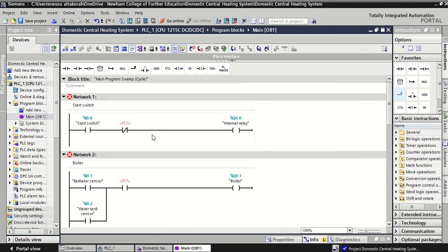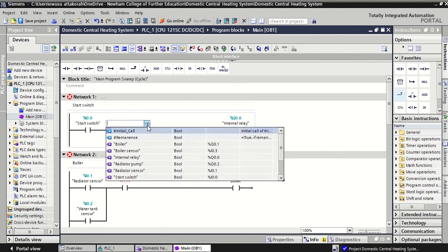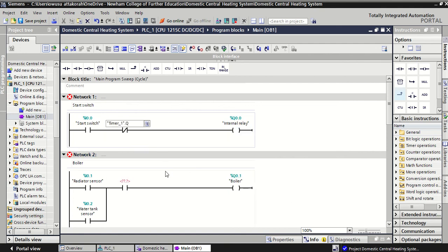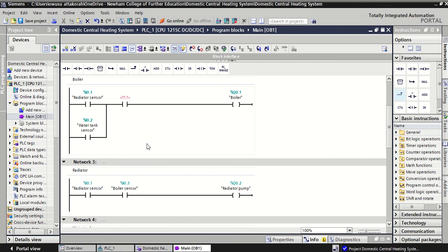The first cycle is the system staying off for 20 hours, and then coming on for 4 hours, and then that cycle is complete. So after the cycle is complete, the second timer, which is timer underscore 1, should interrupt the whole system and begin again. So I'm going to use the output of that one here.